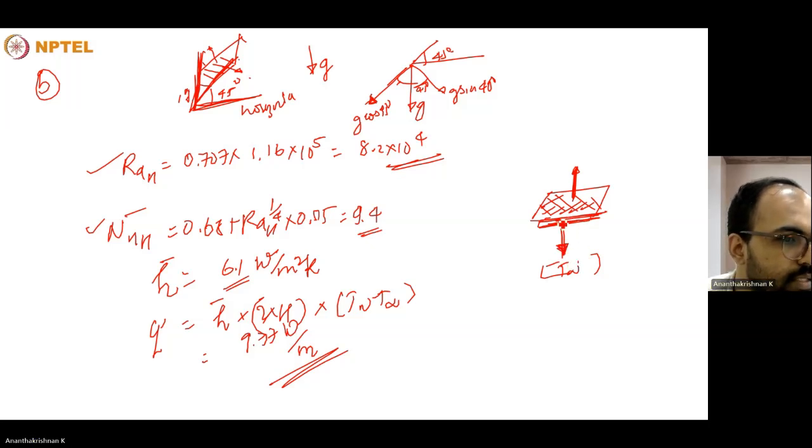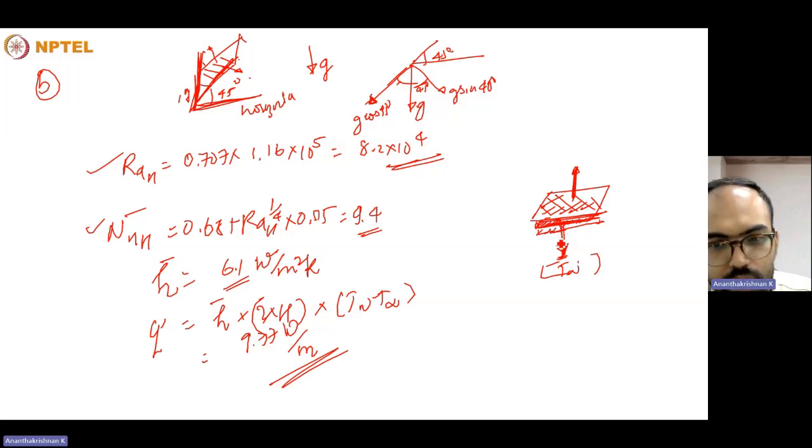Since denser air is colder air and lighter air is hot air, the lighter air keeps forming layers near the plate, resulting in stratification and poorer natural convection, and conduction dominates in that case. Because of this, the total heat transfer rate will be much less compared to that of a vertical plate.